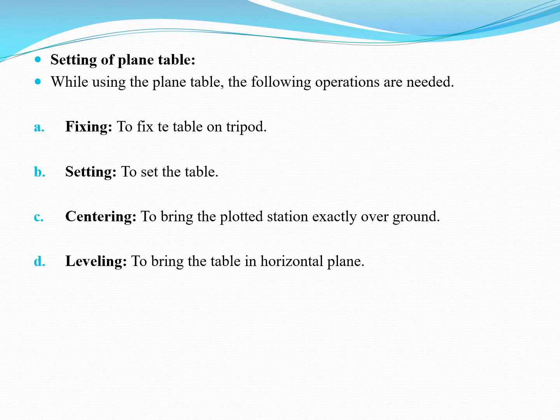Next is the setting of plane table. Setting of plane table is done before making any measurement and plotting. Following are the different steps performed for setting of plane table. Next is centering. To bring the plotted station exactly over the station on the ground, we do the centering operation.